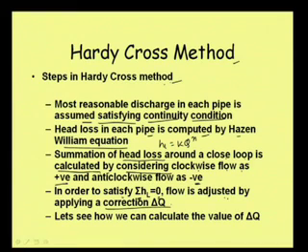correction delta Q. So, once we get the head loss in each and every pipe of each and every loop, then we check what is the summation of head loss in each loop, and definitely with our first assumption this will never become 0, so we need to apply some correction.